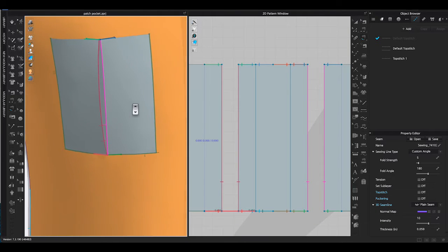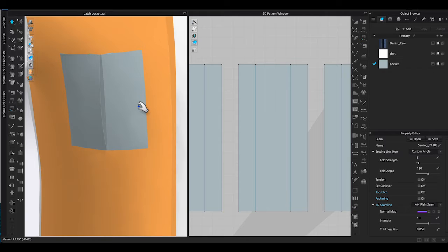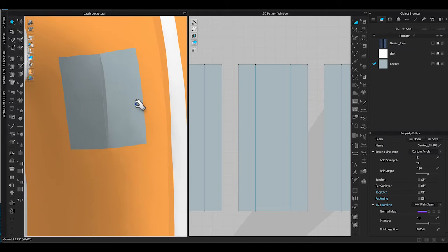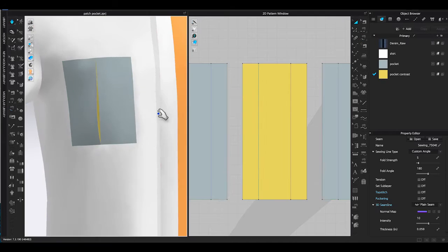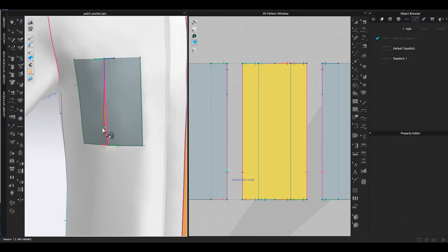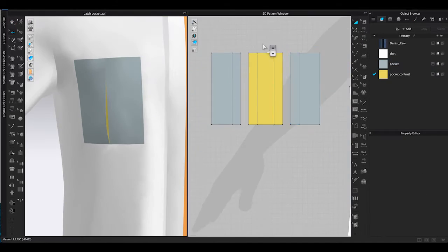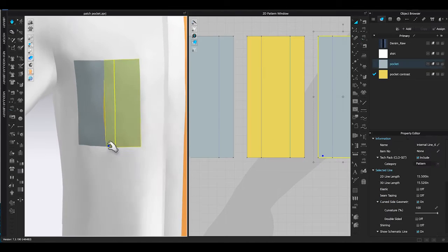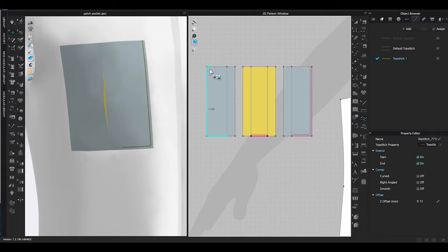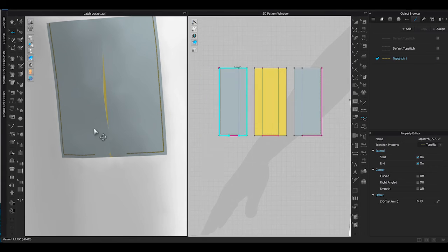Next, use free sewing to close the top and bottom pleats on both sides. Click Simulate, and the inverted box pleat pocket is done. You can make the pleat opening smaller by sewing the pleats together. Add top stitching to give a finished look.